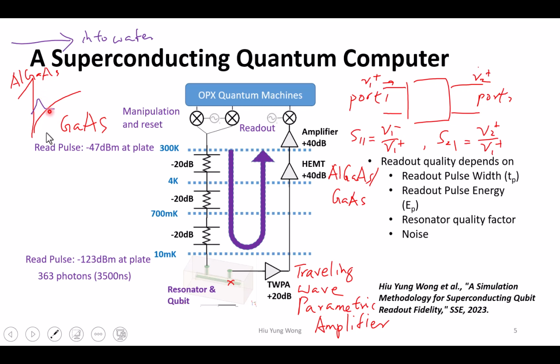But anyway, how are these electrons formed? They actually come from the dopant at the barrier. So this ionized impurity is far away from the electron, so they don't feel the Coulomb scattering, right? This is purely device physics. And so they will have very high mobility, particularly at 4 Kelvin. We're talking about maybe 10,000, or 40,000, 100,000, right?